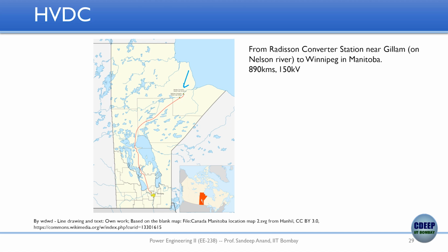And then you generate AC power. Of course, you step it up using a transformer, then you convert it into high voltage DC using mercury arc valves, and then the DC power flows in this direction and comes to a place called Winnipeg, which is a reasonably big city, right, where the loads are. Then again it gets inverted into AC, steps down using a transformer, and then you can use the same voltage levels for residential and commercial applications. So finally it lands up here.